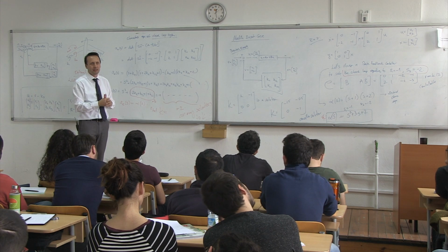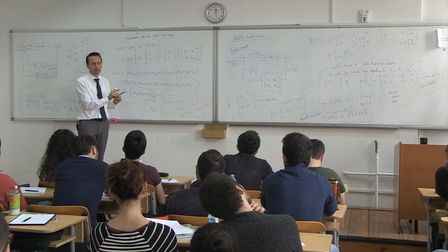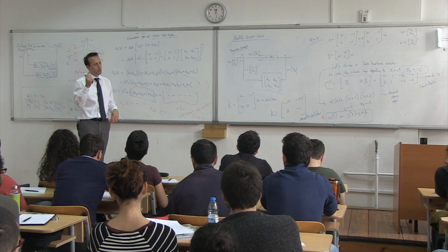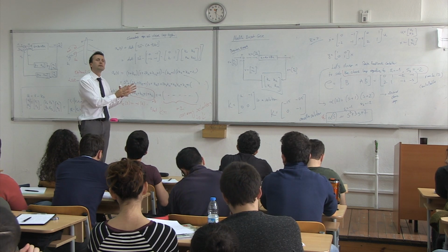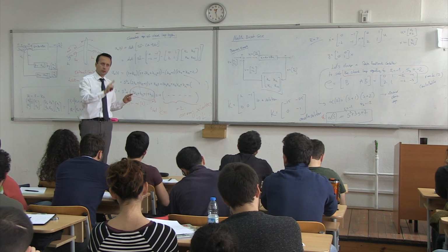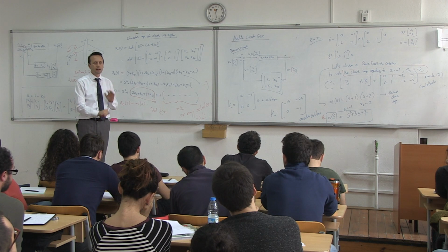There's one solution, if you just want to place the eigenvalues the way we put it. You can't really. It's a 4x4 system, one control. You can move everything to one place, to the eigenvalues, and for that, you have one control. Therefore, your k value, your feedback gain k, is unique.